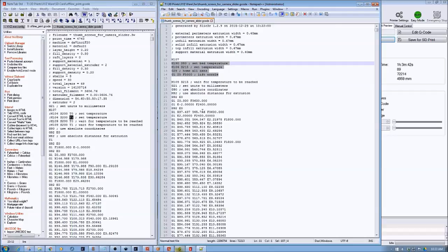One thing I want to do is see if I can get the bed on the 2.0 to warm up a bit more than under the standard, because I'm having a lot of warping issues. It's only reaching about 60 degrees C, where my 1.0 is reaching 90 degrees C, so there's a 30-degree delta. I think the plastic extrusion temperature is okay, though it could be a little warmer.